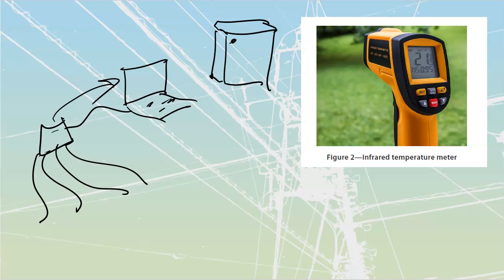These are simple checks. The oscilloscope, the temperature meter, the Crest Factor, all of that is going to be simple checks that you can do that'll tell you that there's some problems, but they're not necessarily going to solve it, nor are they going to tell you a lot about that. That's going to be the next learning task we're going to look at, solving these things using our power quality analyzers.